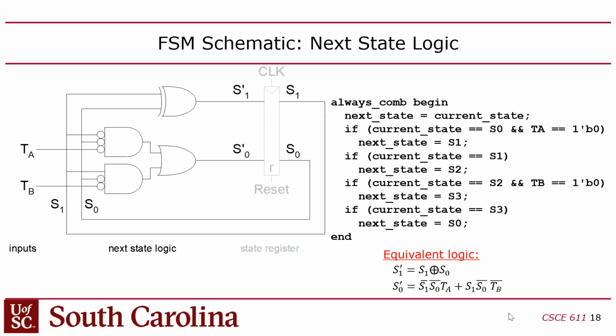if we know that the current state only changes once per cycle, but the inputs don't necessarily have that restriction. So what may happen is that if you're in state S0, the traffic at the academic light or academic avenue, the road traffic sensor, may toggle up and down several times within a clock cycle. But this logic won't notice that. It only cares what the traffic is on the rising edge of the clock, right?